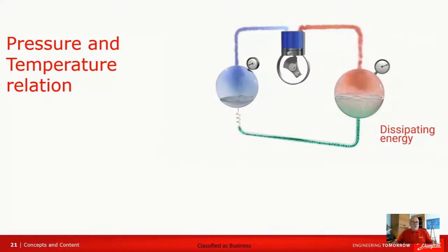And there's a question about what would flash gas be. Yeah, that's another good one. Imagine that somebody is actually, if you look at this circuit again, if you take a hammer, to be very, very careful, you shouldn't do that. Please don't. But if someone is actually jumping up and down on this line here, and it crumbles down, and you get a narrowing of the liquid line, and that's important. On the liquid line, you have a narrowing.